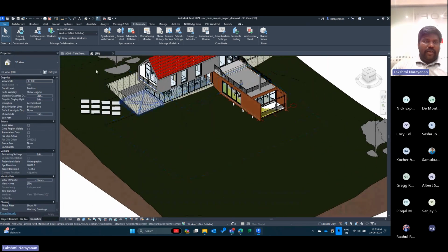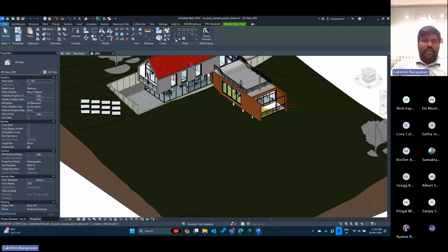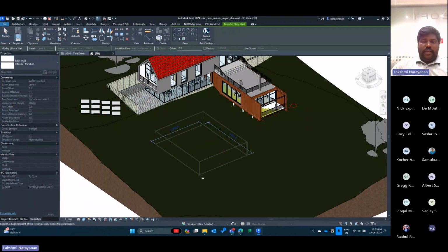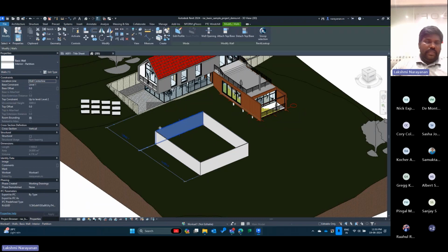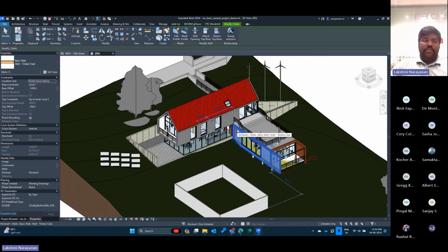They can have the design open and work on it. As you can see here, this is the design data which I just created, four walls, and it is flagged as edited by the current user, the username of whoever is logged in to Revit. Any other elements available in the design are unowned by any person, so they are not edited by or checked out to any person.